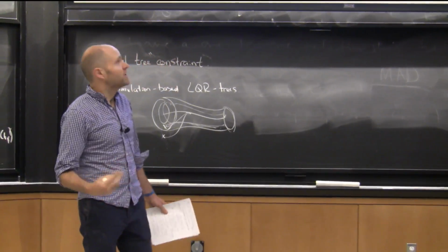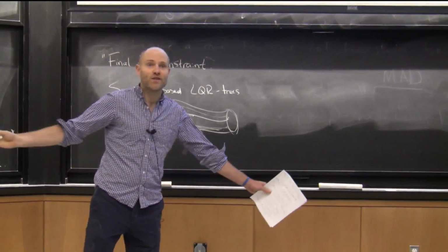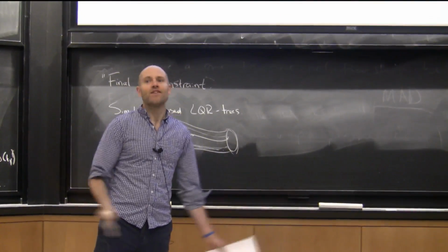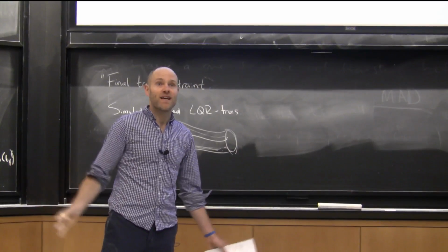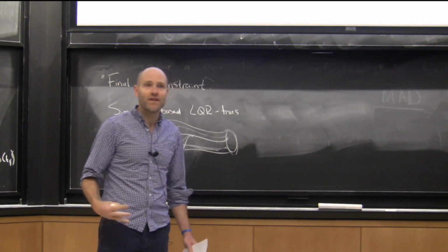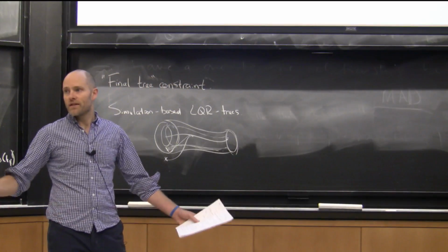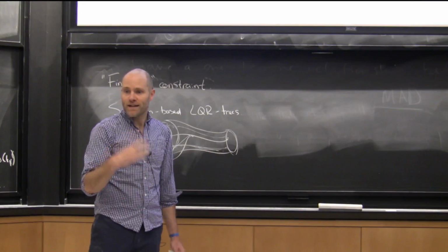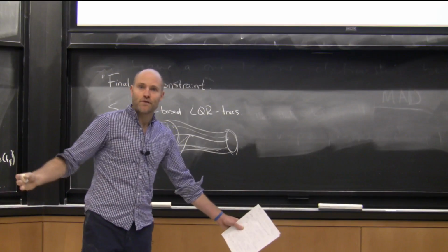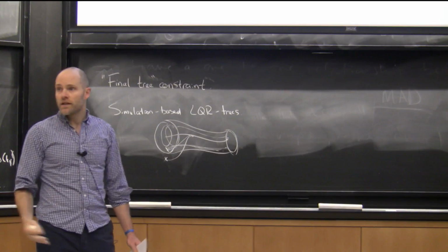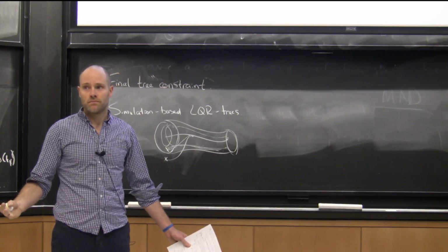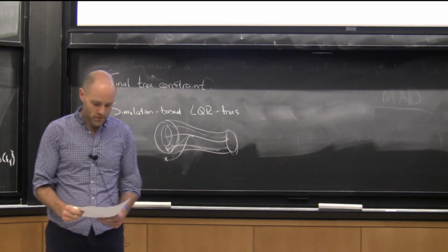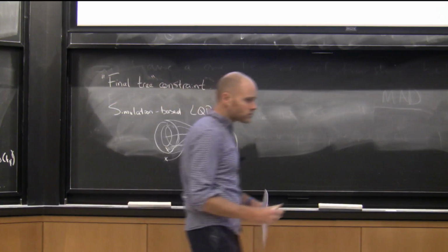Well, you find a state that's outside the region of attraction of your initial controller, you design a crazy maneuver, and then you see what the set of states is for which that works, right? And eventually you fill your space with a handful. The claim is that if you've got a good stabilizing back end here, a small handful of these sort of recovery maneuvers can cover a large part of space. And in practice, that has played out for the systems that we've pushed this on.